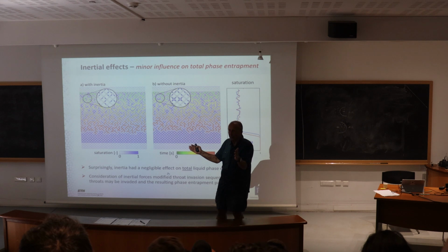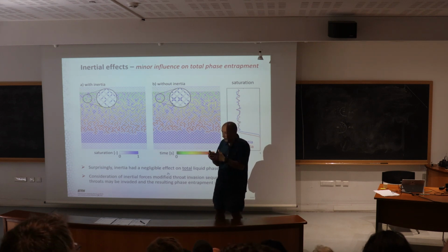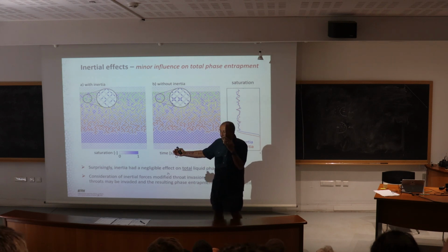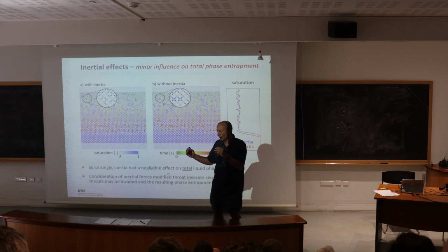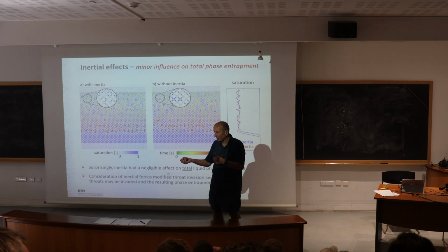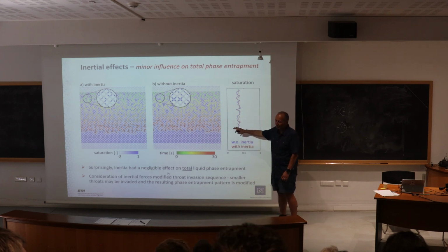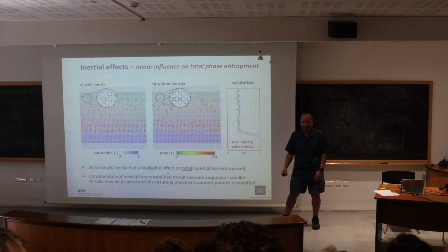And there is a characteristic length, Reno helped us calculate some decay along the front, how far from the jump I actually feel the pressure jump and stuff like that. It dissipates very quickly. So on balance, I would say that in smaller pores, I'll have faster jumps, but I'll have much more viscous losses. So I think it will not radically change the picture. That's my thinking. Okay, yeah.